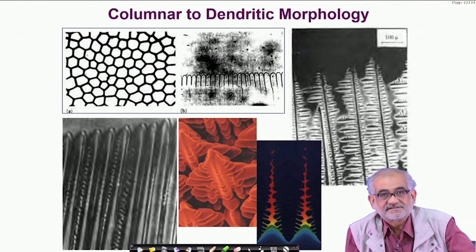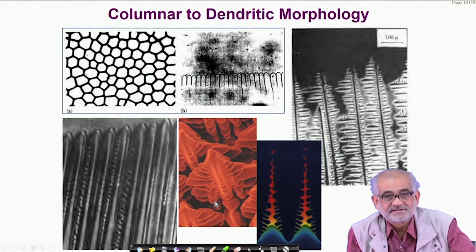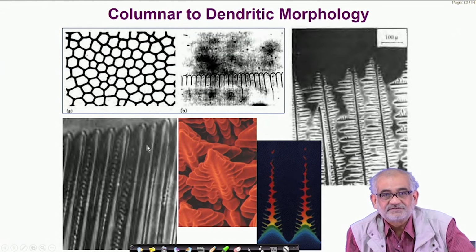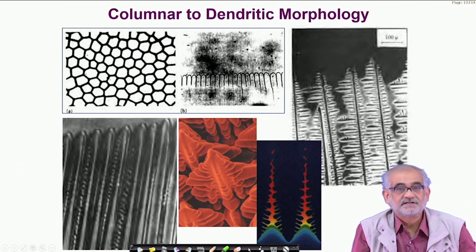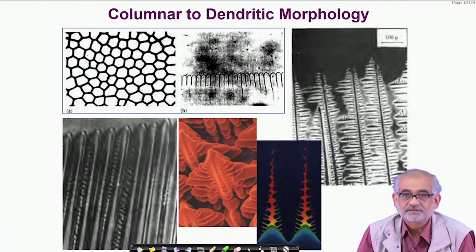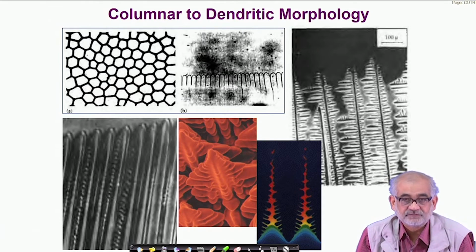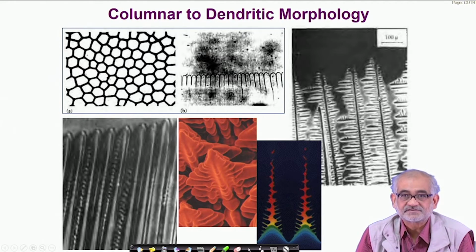So, when we cast, these are the kind of fancy structures we see, not always, but we may end up actually seeing such growth of columns, and at times those columns which are unidirectional in nature of growth can also manifest themselves in a similar tendency of growth in the lateral directions, leading to what is known as dendrites, which is essentially borrowed from the Greek word which means essentially fir tree-like structure.